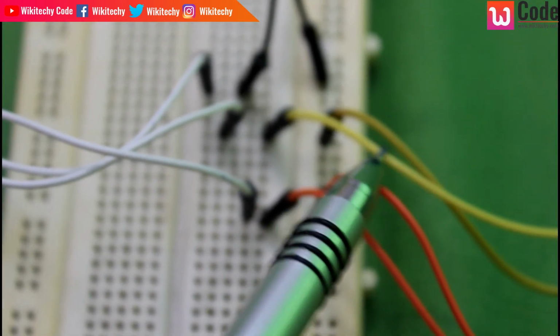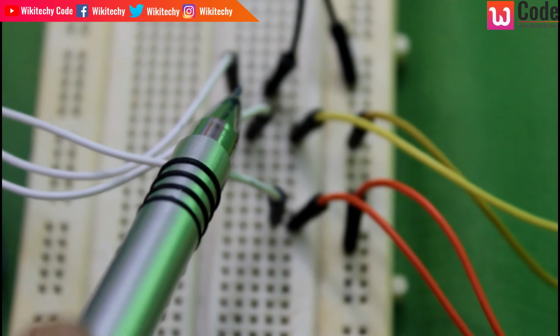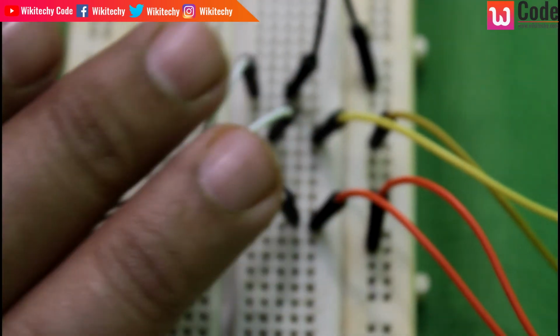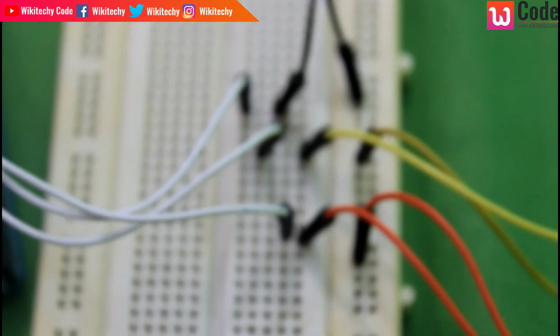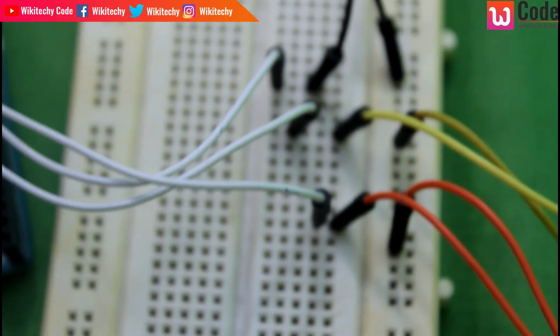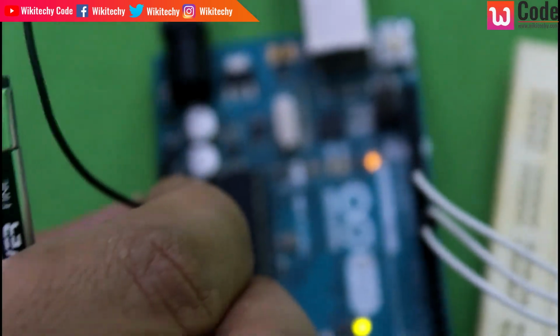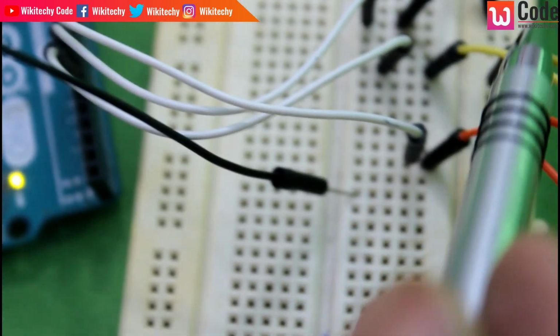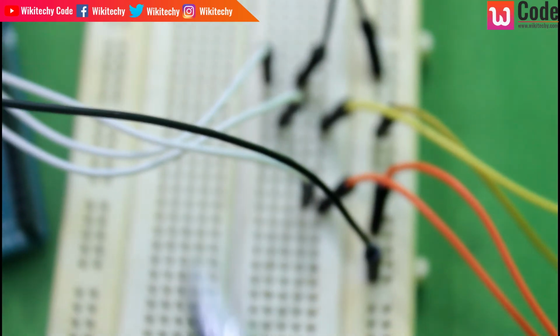The other wires 1, 2, 3 are connected in the boards, and these wires are connected with this one. So one wire of the speaker will be connected to one wire of Arduino, and this is the circuit. You are able to see it here. So these two are connected, these two are connected, and these two are connected. Now what I'm trying to do is, I got my ground pin here. All the three wires are connected to the ground pin. So I'm connecting to the ground pin now. Everything is connected here.